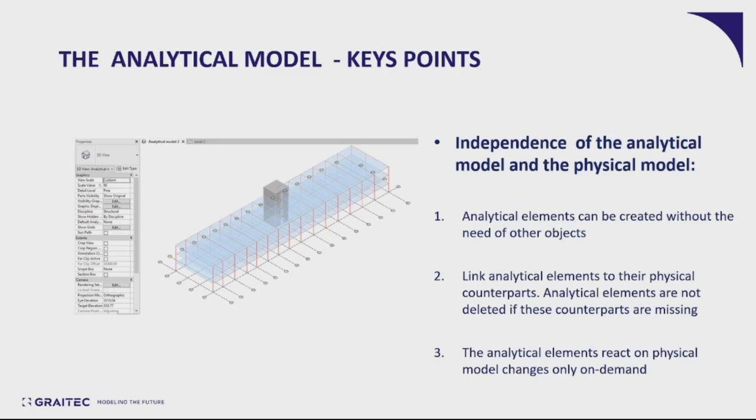The analytical model is independent of any physical model that exists in Revit. The analytical elements can be created without the need of other objects. You can link the analytical elements to their physical counterparts. Analytical elements are not deleted if these counterparts are missing. And the analytical elements react on physical model changes only on demand.